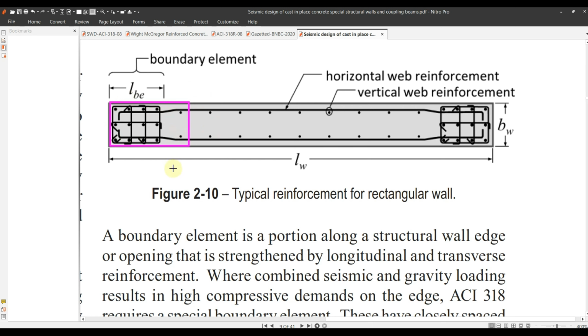But say that it is a wall I have designed. Now you are reviewing it, and you can say to me that the edge length should be 38 inches, and in it you must provide 14 inches of reinforcement, and 38 inches again here, and then you have a certain area left here. Then I may say to you, what about the reinforcement here? I can take the benefit of it also, right? So this can be covered by the uniform reinforcing method or the general pier section method.